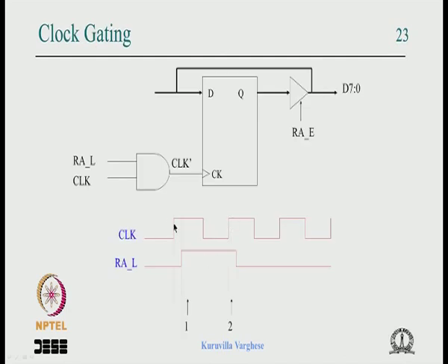Something happens to the state machine, it changes state and the output is decoded. So the output comes delayed with respect to the positive clock edge. There is a TCQ, the state flip flop delay, and TOL, the output logic delay, and it comes here.